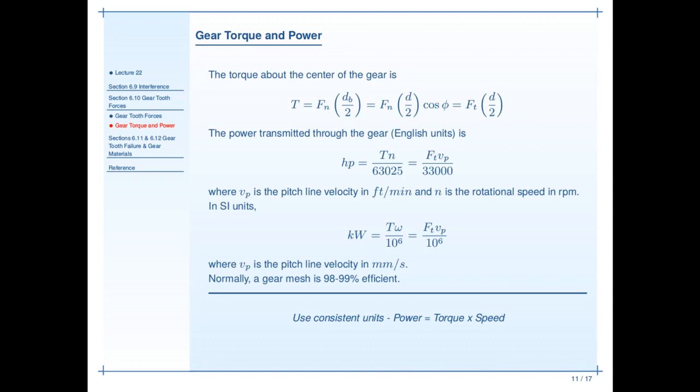This is an important insight, guys, and it's worth spending just a moment on. Whenever you're looking at any engineering problem, it's well worth your time to try and do some kind of a power balance or energy balance. If you're doing this, you can equate, for instance, the amount of electrical power being put into a system in watts with the amount of mechanical power. So generators can work this way, electric motors can work this way. You can see what your electrical power in as compared to your mechanical power out is, and therefore get an efficiency number.